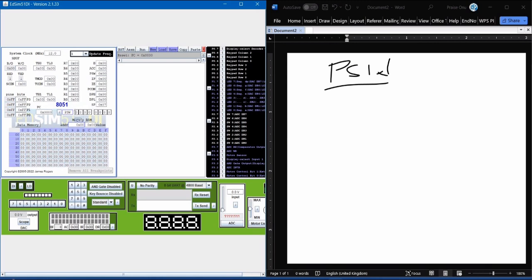You can see that you have the CY. The CY is called the carry bit. The next one is the auxiliary carry. Then this F0 is for user bits. That one is user defined, depending on what the user wants that particular bit to do. Then there are the RS bits, RS1 and RS0. They are more or less like register bank selectors.